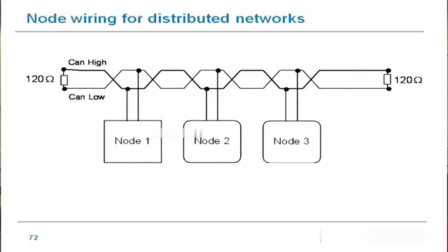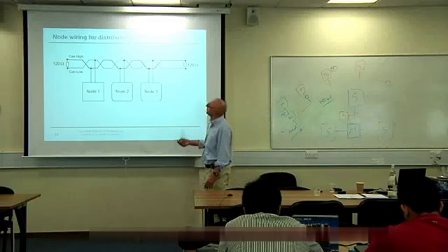This is what the physical layer looks like typically. It's twisted pair cabling. If you've done any work with RS-485, it's just the same cabling that would be used in an RS-485 network. That's not an accident. That's essentially historical, and some of the factory settings can switch over quite easily between a traditional RS-485 network and a CAN bus if they want to do so, running over this.